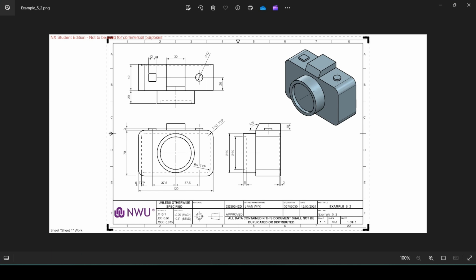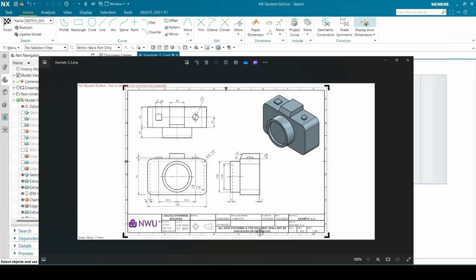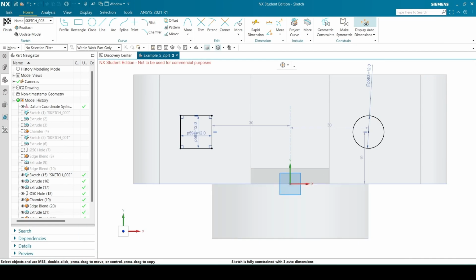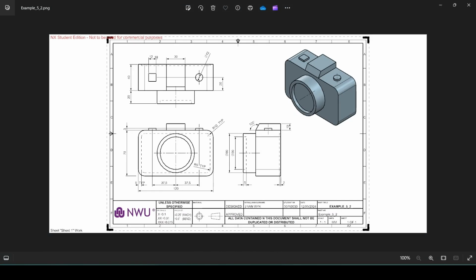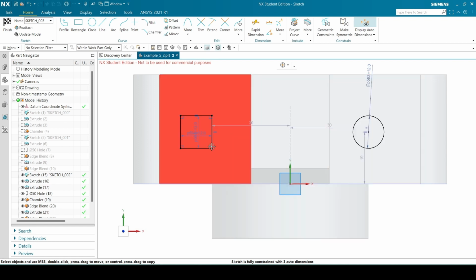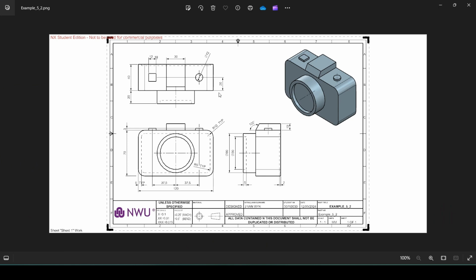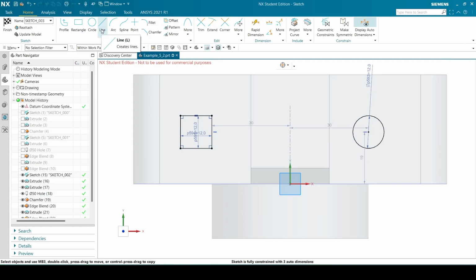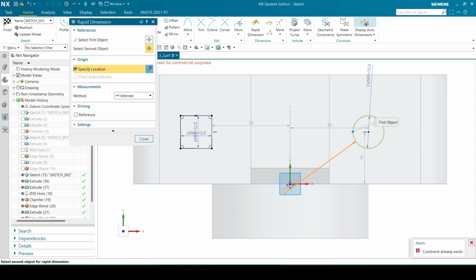Then both of them are 20 millimeters from this front here. I made the whole model and all of the sketches so that most of the reference dimensions are from a single point, that point there as the origin, so that I can reference everything from it. It's just easier, and you don't have to do a lot of maths about where you are.